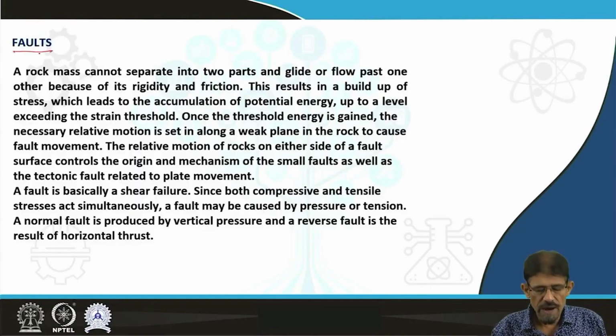Faults. A fault is one of the major structures formed under the brittle domain, caused by tectonic forces or by simple deformational forces, but due to deformational forces the dimension of the fault is limited. Here the rock mass cannot separate into two parts and glide or flow past each other because of rigidity and friction.